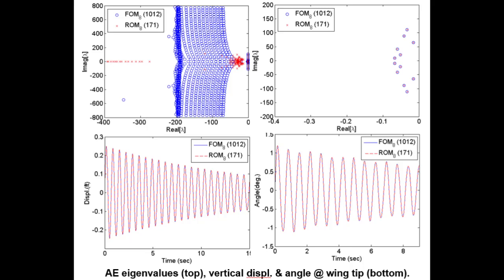When the same parametric reduced order model is tested for mu sub 8, which represents the most severe variation from the nominal values of the 8, again we get outstanding matches in both the aeroelastic eigenvalues and time histories, proving the validity of the parametric reduced order model.